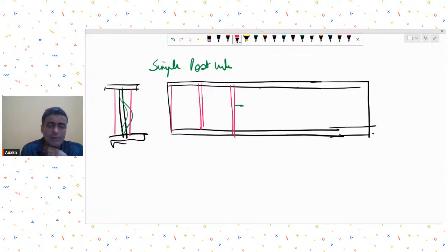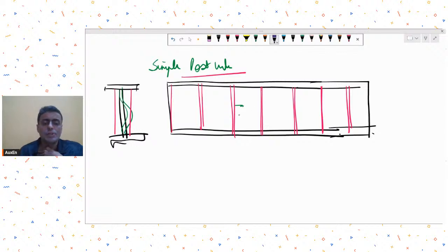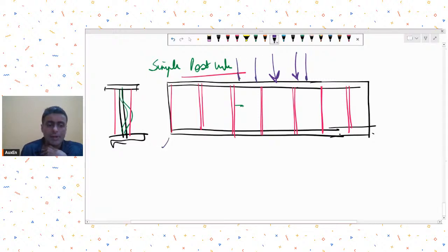Now let's say I have provided these end stiffeners and I am calculating the web capacity based on the simple post critical method, which assumes web buckling. Now if I were to increase the load even beyond that value, let's assume a simply supported case just for simplicity.